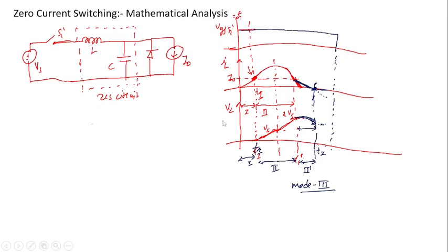So our question was, at time T2 in mode 3, what will happen? Will the inductor current in reverse polarity be observed or not? Which means, can the inductor carry that negative current? Here, I am talking about this inductor. So it depends on the switch nature. I have mentioned we are assuming this switch is an SCR switch, which means it is shown with a diode-like polarity, with anode and cathode,